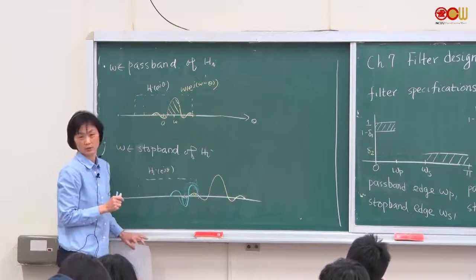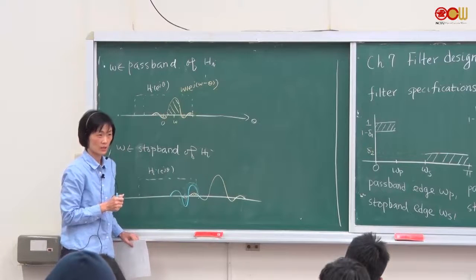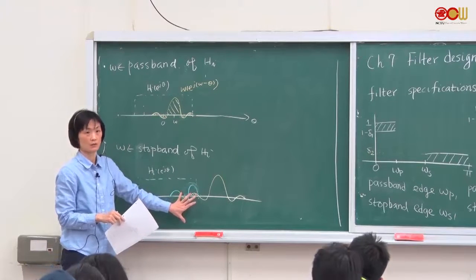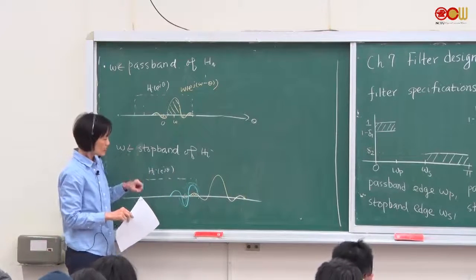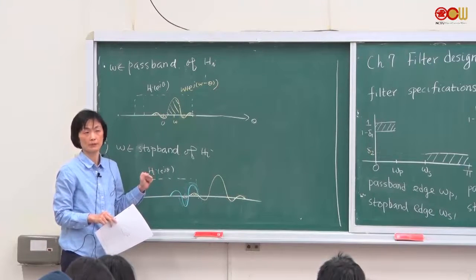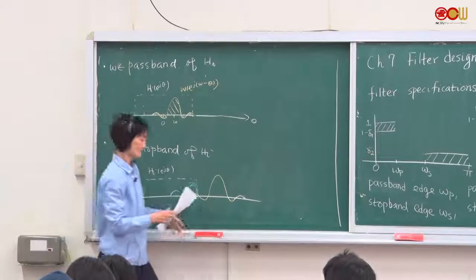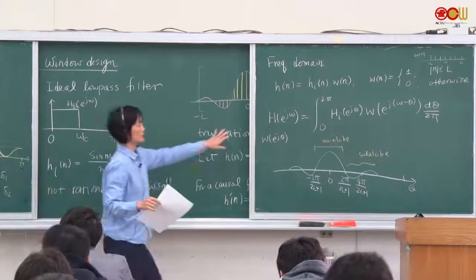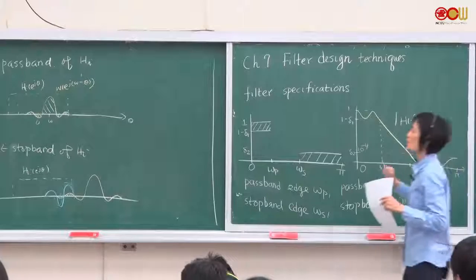If the side lobe is very big, then will there be a bigger variation of the result of the integration? Then it would affect the integration more, right? So we can expect that we will get a larger stop band ripple if the side lobe is bigger.